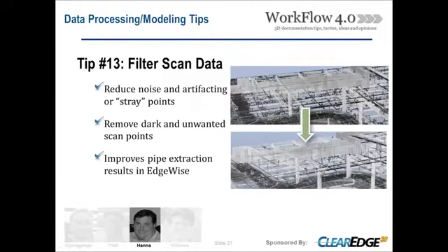Another process that we do here internally, again thinking about our ultimate end goal, providing a good deliverable: we have found that when we're running tools like Edgewise, when we clean the scan data up, run through filter routines to reduce stray points and artifacting on the pipes, removing dark points or unwanted scan points, we're really yielding much better results when we're running the auto extraction pipe tools.